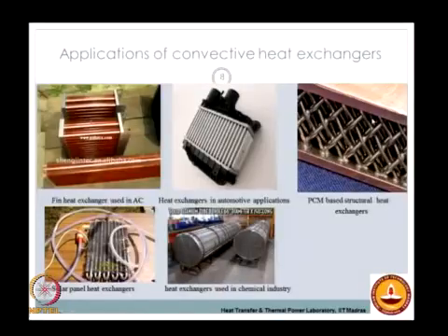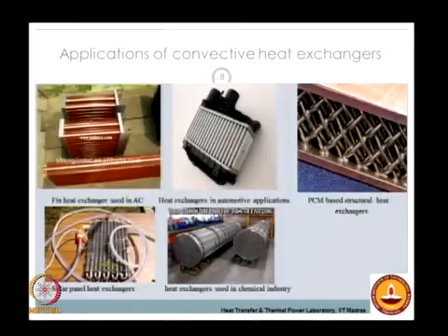In the next half of the cycle the cold fluid flows through this medium, and this releases the heat back to the cold fluid, where the cold fluid gets heated, and in the process of losing the heat the phase change happens again from the liquid to the solid phase, so it solidifies. So the material repeatedly melts and solidifies continuously depending on whether you are using the hot fluid or cold fluid, and therefore can indirectly transport the heat from the hot fluid to the cold fluid.